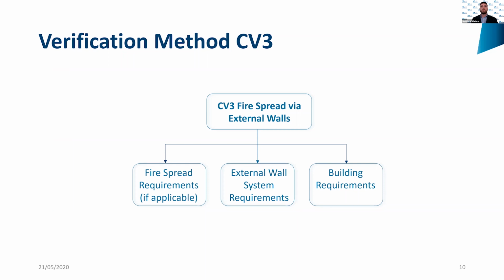Now, most people would probably be aware that there's a standard, AS 5113, which is the full-scale test standard, and it sets out the procedures for testing and classifying external walls according to their ability to limit spread of fire across their surface.